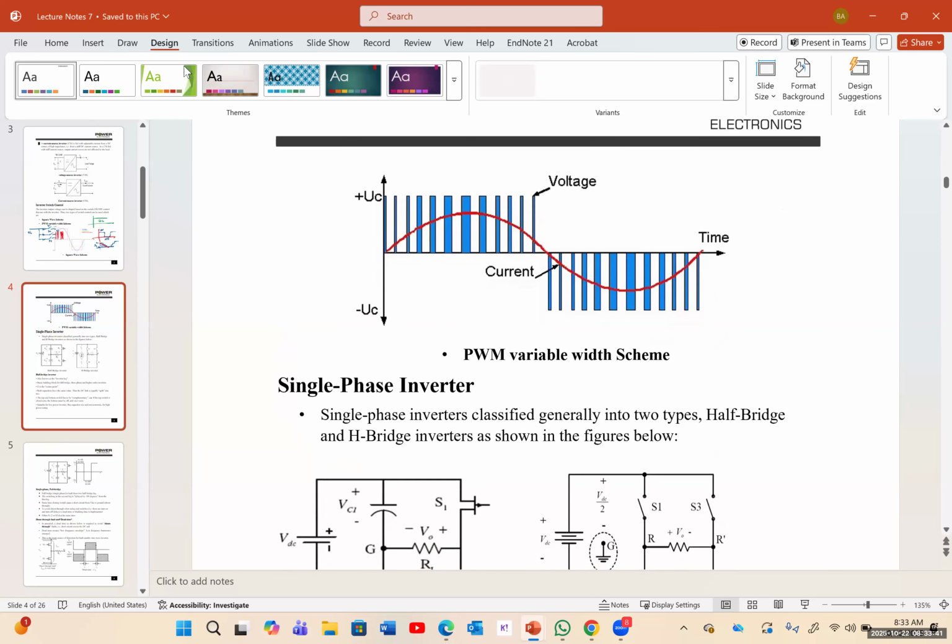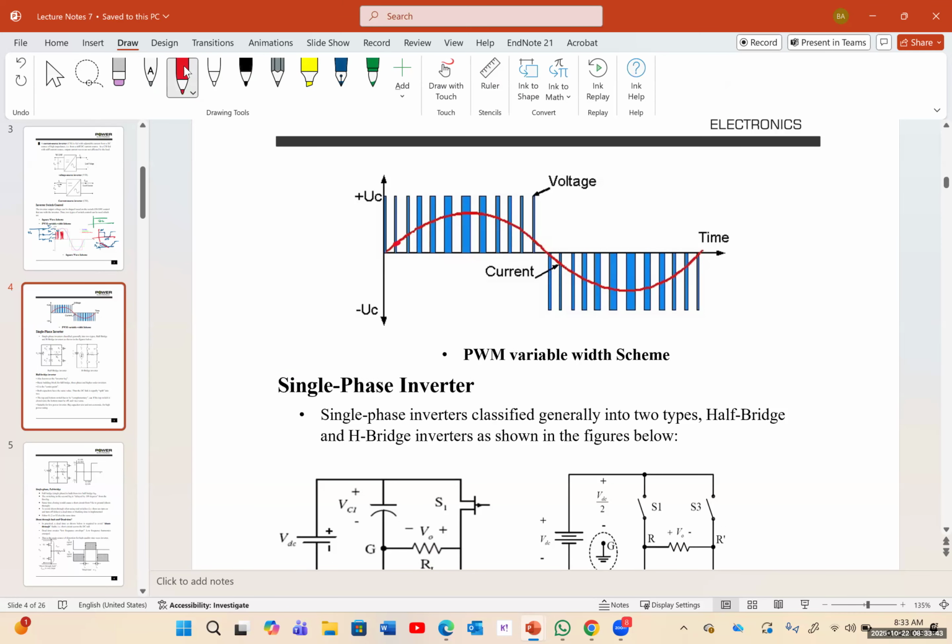sine wave. And what this does is technically, when you have a small, the average voltage is here, then the average voltage is here, and then it's basically connecting these voltages together. Okay. So you're connecting the samples that we have. Let me draw it with a different color. So basically what you see in the output is a bunch of dots, and then you can use a capacitor filter to connect these dots together and create that perfect sine wave.